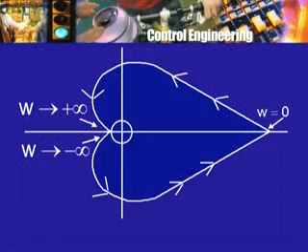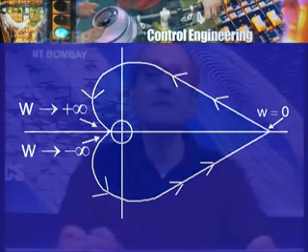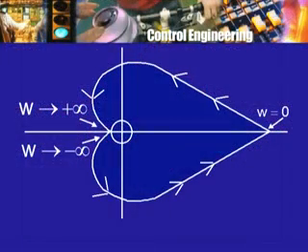And as is obvious, you can only apply frequencies up to a certain upper limit. If a frequency is too high for a system like a motor, it will not make any sense; the motor will hardly turn if the frequency is very high because of its inertia, the inertia of two kinds. So, there will be an upper limit on omega, maybe up to 10 kilohertz. So, this response will stop somewhere, the measurement points will end up somewhere here, and one is now extrapolating to go beyond that, trying to guess what will happen when the frequency is increased indefinitely.